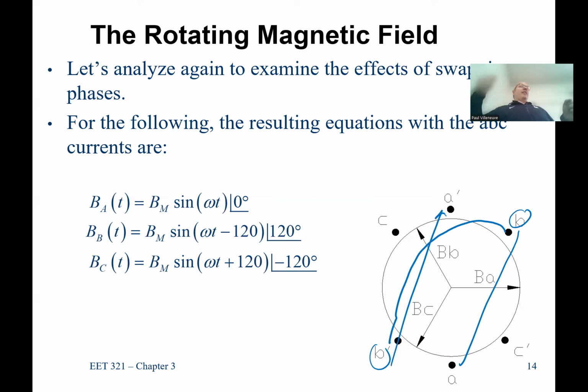You're taking the wire that carries the A phase and the wire that carries the B phase, and you're switching them. You don't have to worry about the other end, and why it might say, why are you doing that? That's because they're internally connected. It's either a Y or delta. So when you swap them around, they automatically get swapped around. But in reality, what's happening is the current is coming back through there on the A prime or B prime line.